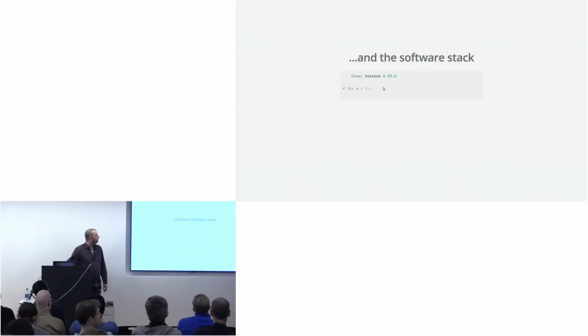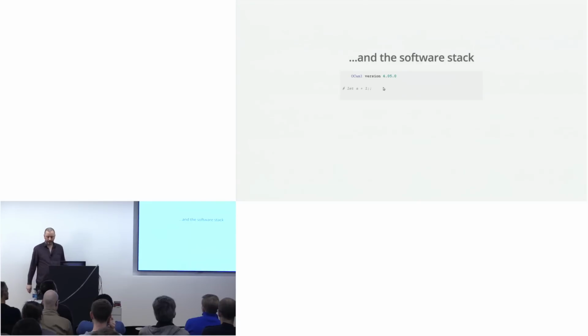Now, where all that OCaml came from is the software that we'll be running. So once the FPGA loaded, it started with this custom bootloader, which then loads a program from SPI Flash and copies it into DDR memory. And that is an OCaml top level, and I'll talk more about what that is later. I should say, those LEDs you saw flashing were actually driven by the bootloader. So as it loads every something like 64K, it increments a counter and then outputs it on the LEDs.